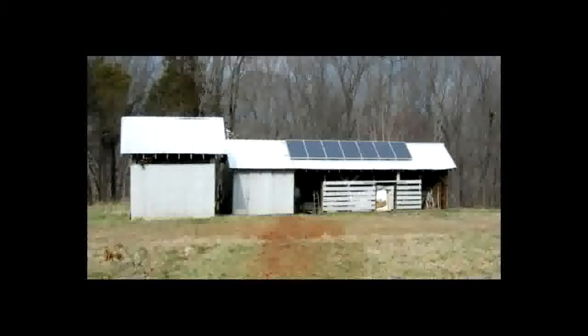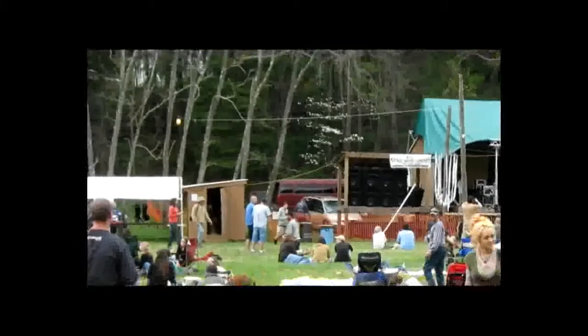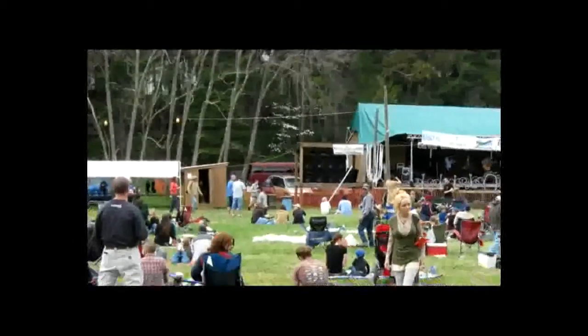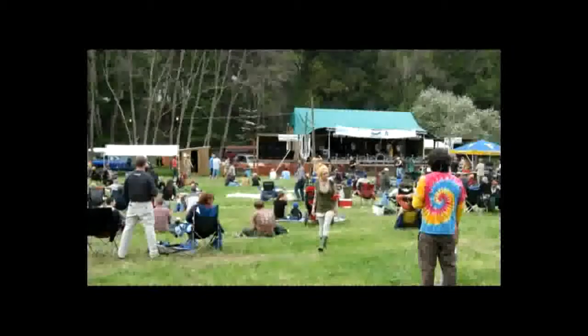A kilowatt hour is 1,000 watt hours. And that is the number that you usually see on your electric bill. So what is a watt hour? The way I like to explain it is if you have a 100-watt light bulb, and a lot of people have seen those in their days, a 100-watt incandescent light bulb. If you burn that 100-watt light bulb for 10 hours, 100 times 10, you've used 1,000 watt hours.